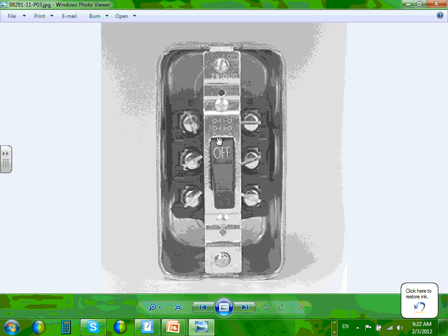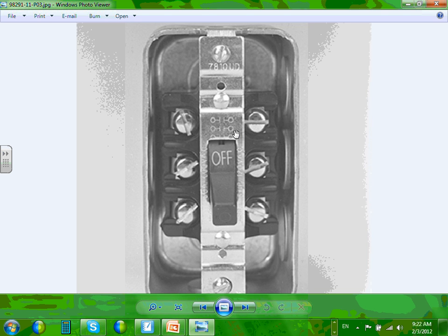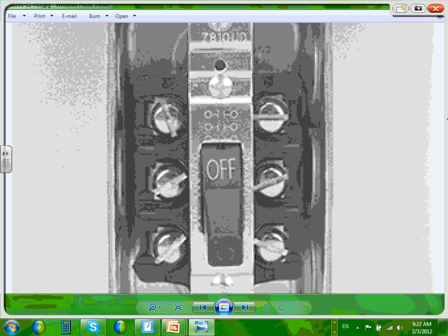Okay, a couple of contacts and timers. This one is a relay, NEMA 1 enclosure. I don't know if you've seen relays in ours. I want to just open this one and you can see the contacts that come with it here, the normally open contacts: 1, 2, 3. So 3 contacts. What does that mean? I can drive 3-phase out of that. If I have 3 separate contacts, I can drive a 3-phase load out of it. And the rest of them will be where the coil is going to be located and so forth.